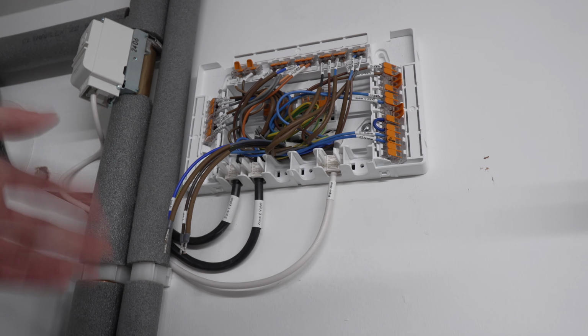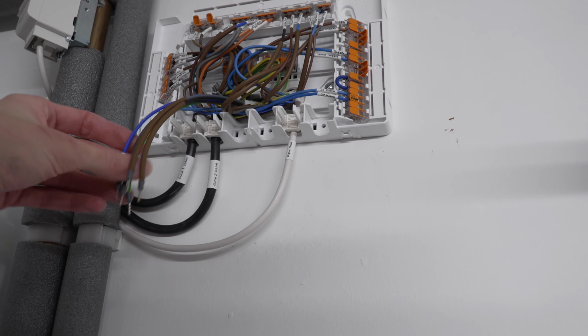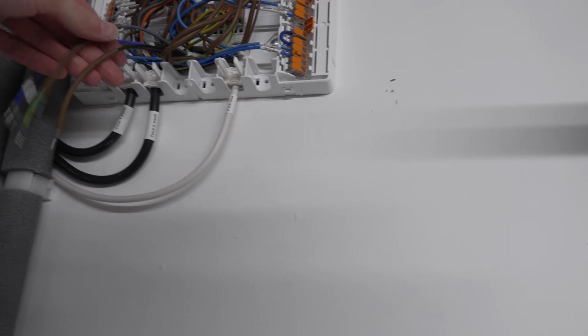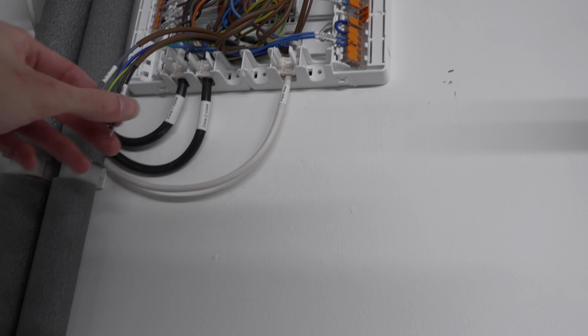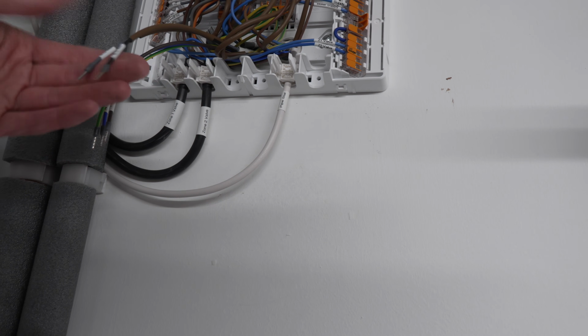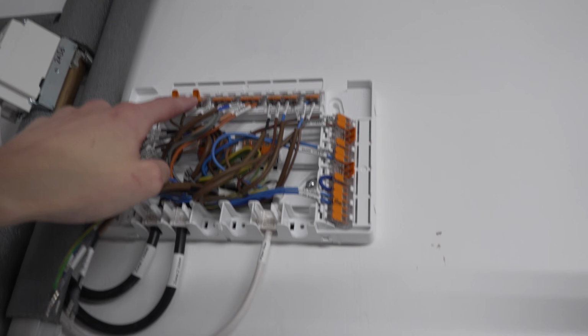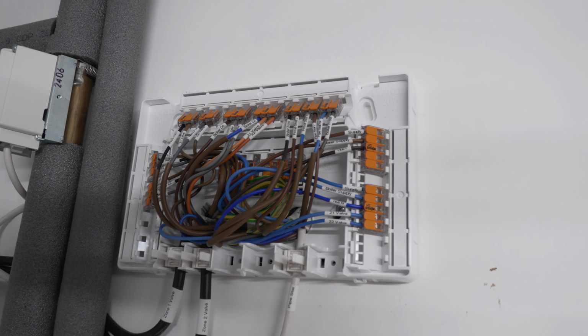And then up here at the wiring centre, very similar idea. The brown and blue are the line and neutral to power the hub, so they'll go into the permanent line and neutral terminals over here. And then we have our two switch lines with the sleeve that slips down. So once again, grey is zone 2, black is zone 1. These will then connect up to the zone valve terminals up here where the old thermostats used to connect to. So there we go, that's it all now connected.